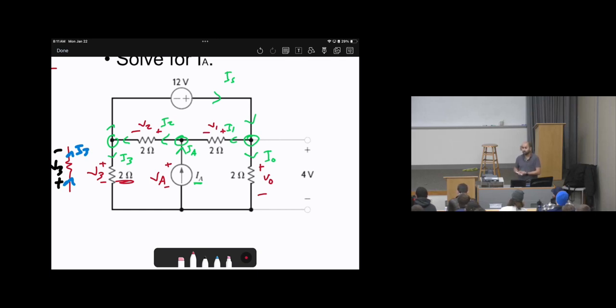Yes, we have 4 volts, right? So we have 4 volts given. And you can locate the positive here, the negative here. This means this is the same as the voltage at the element VO. Is this correct? Because it's in parallel. Or assume that this is the terminals of the digital multimeter. So you put the positive sign, the negative sign, the reading is 4. Therefore, this is the voltage of this element. So I will say here VO equal to 4 volts.